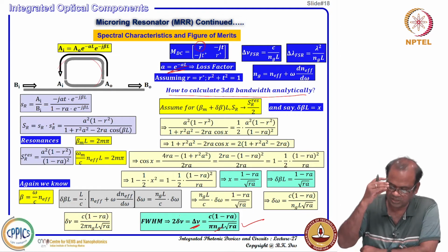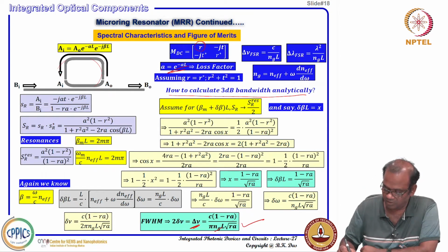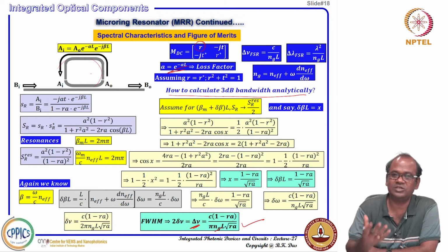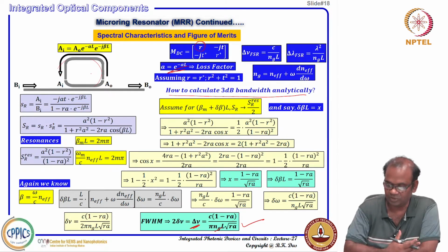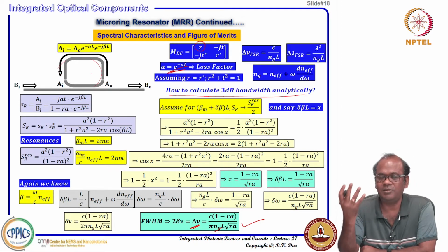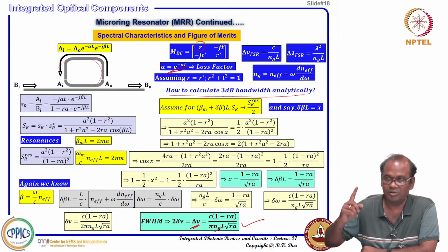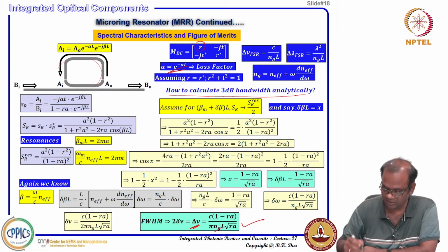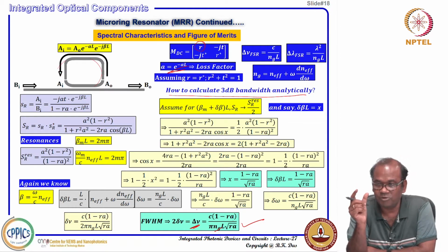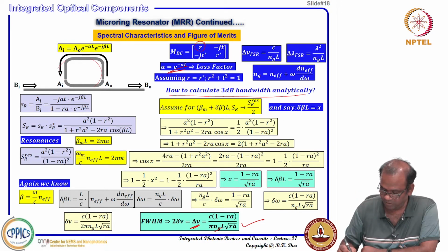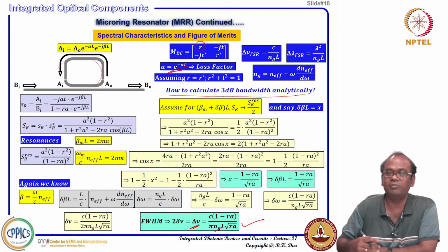Okay. So, this is interesting. From the waveguide design parameters, you can design a ring resonator to expect a certain full width at half maxima. If you just increase, for example, the L value, the length of the ring resonator, then delta nu, the full width half maxima, will be narrowing down. And if you somehow reduce L, then it will be broadened.